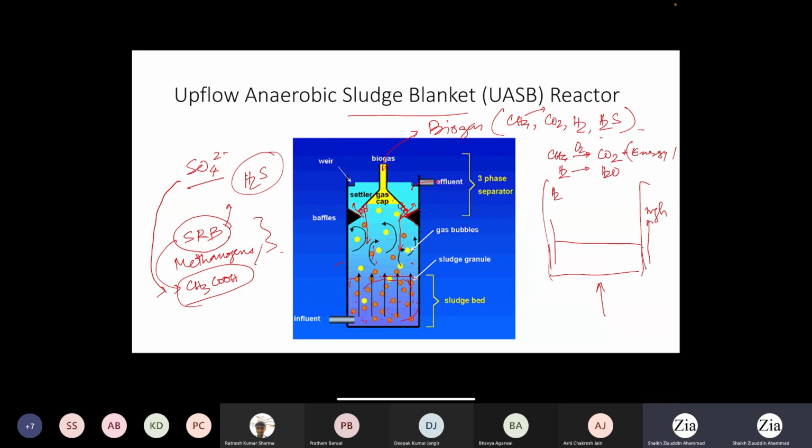Now for H2S particularly, it will get converted to sulfur trioxide, and in presence of moisture, the sulfur trioxide will get converted to sulfuric acid. And sulfuric acid is a strong mineral acid, and that acid will create corrosion. So whatever reactor vessel you have, whatever pipeline you are using for transporting these gases, that entire environment will get polluted by this H2SO4, and you will get microbially induced corrosion in that region.